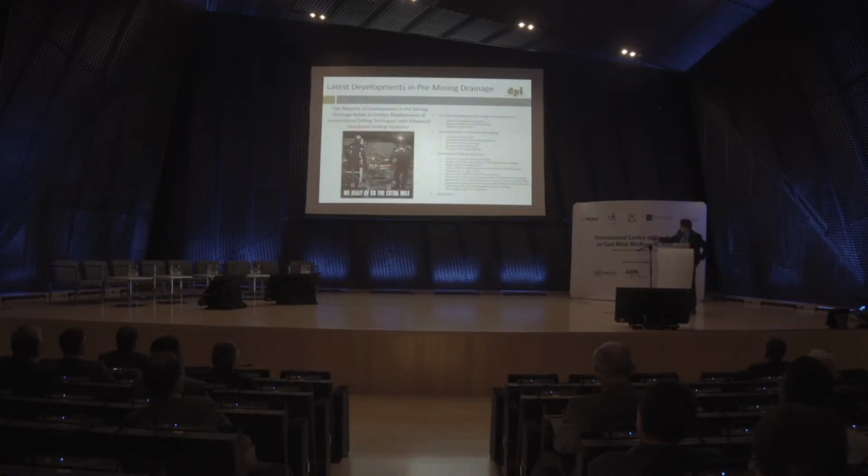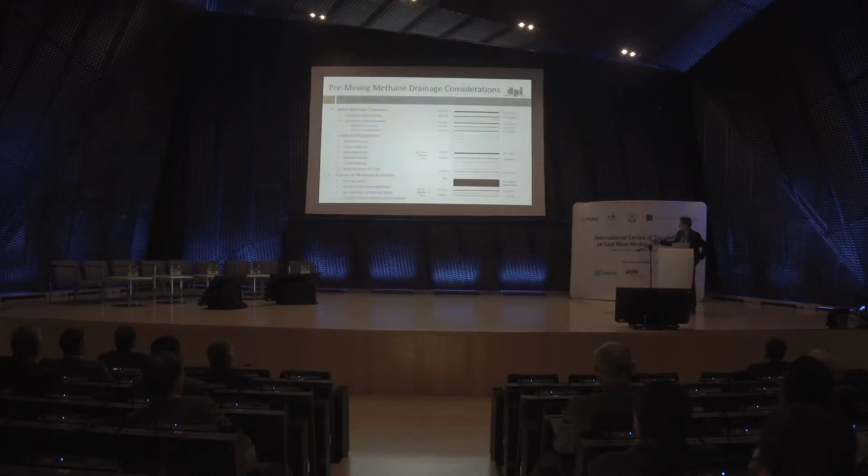And what I'm showing here is really the zone of influence. If we longwall mine the P3, the influence extends 120 to 140 meters up above and 20 to 40 meters below. Take a look at that P11. That's about 200 meters above the P3 seam, and I'm pointing that out because we're going to talk about that as well.